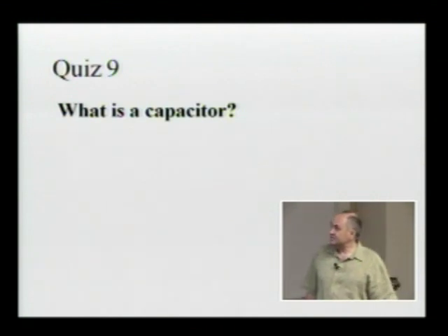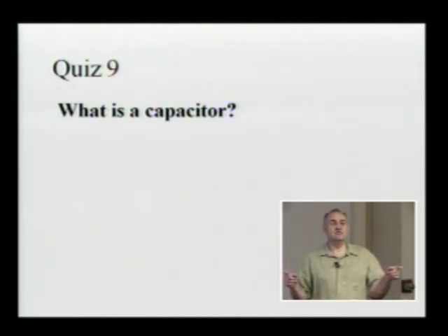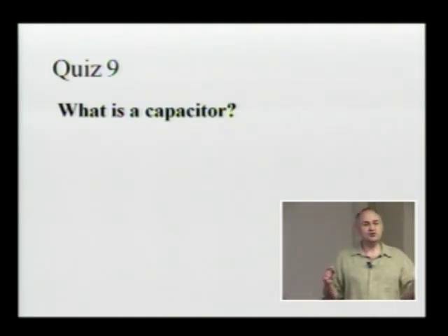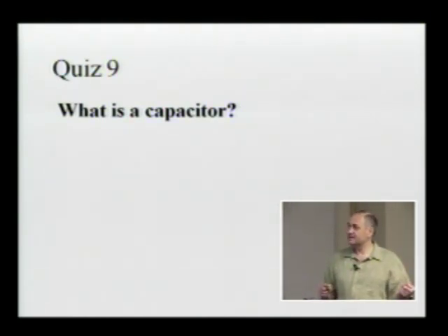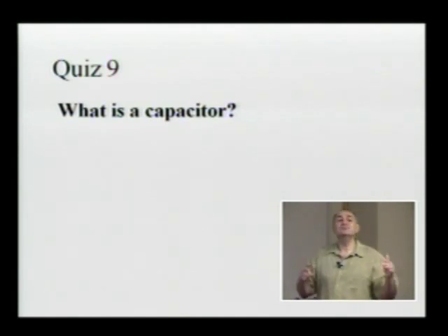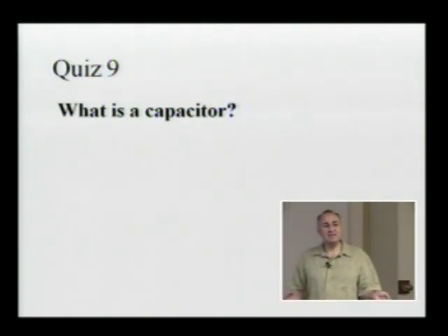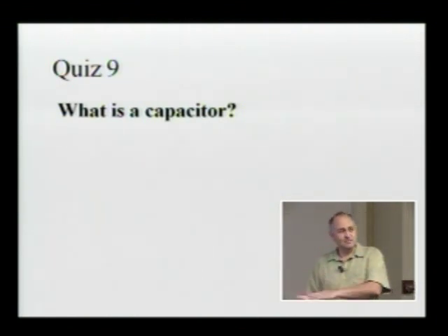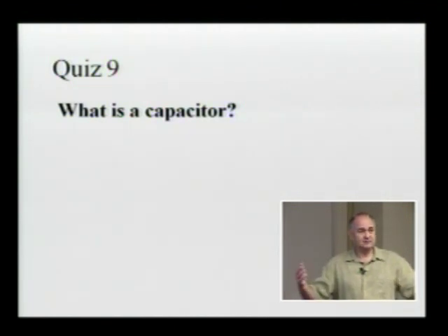So a capacitor is an element for which the potential difference between the two sides of this element is proportional to the charge transferred from one side of this element to the other side. You can also say charge stored. I will accept that. However, whenever you say charge stored on a capacitor, you have to recognize that it refers to charge which is transferred from one side to the other side. The total charge of the capacitor is always 0.